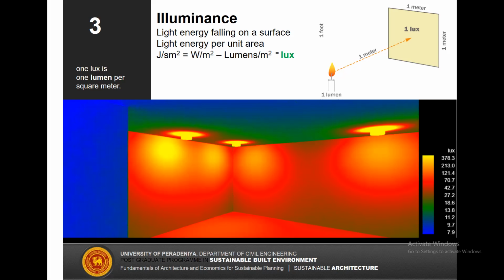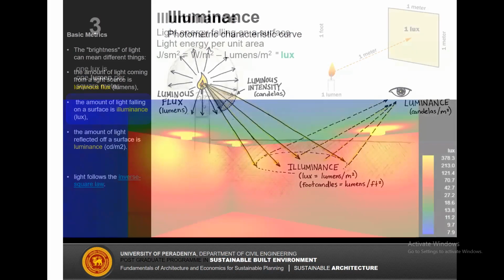When it comes to large scale projects, we provide the 3D model to the lighting manufacturer and he runs this simulation for us in different software. There is software you can download and use, but in Blender also you can do it. Just ask them to supply the .ies files, put them on light fittings, assign that, and then you can run this. Okay.